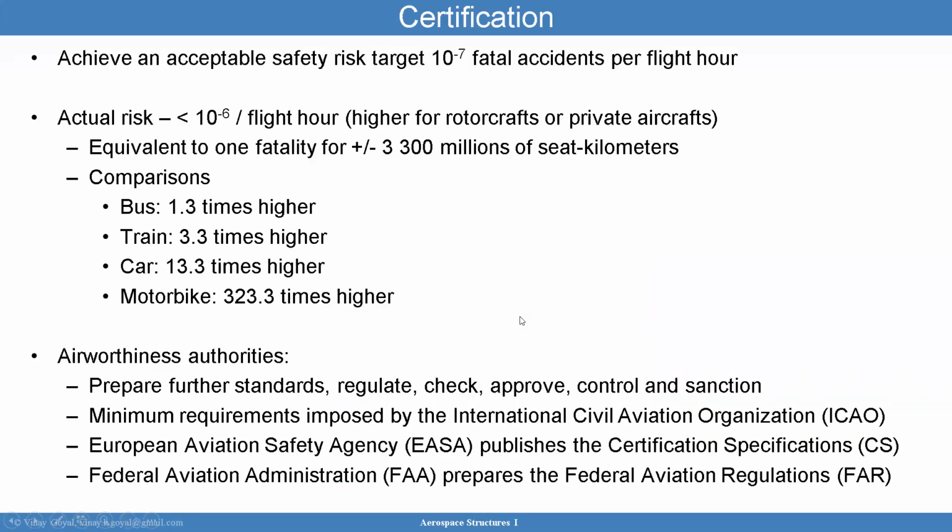To achieve an acceptable safety risk target of 10 to the minus 7 fatal accidents per flight hour, certification is an important aspect of aircraft certification. Actual risk is typically less than 10 to the minus 6 per flight hour and is higher for rotorcraft or private aircraft. This is equivalent to one fatality for maybe plus or minus 3,300 million seat kilometers.